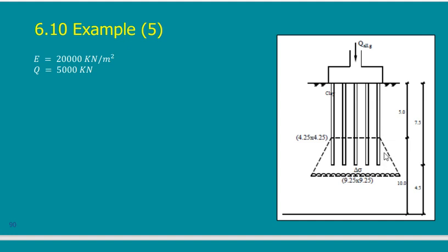So take a line like this with a slope 4 to 1, and from the other side another line 4 to 1, and everything in between will be included in the amount of load that will be carried by the pile. So you have here to calculate two things: the summation of the frictional forces of each pile.